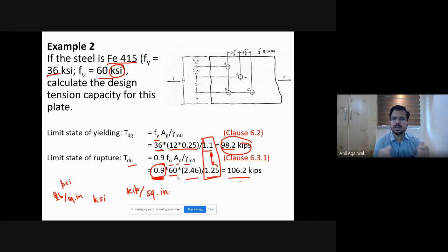What happens is that when you have a plate like this, and let's say you have some imperfections for whatever reasons, like the holes are not perfectly drilled, then the actual rupture strength of the plate has much more scatter, or predicting the rupture strength of the plate is much harder. You understand? So geometry also plays a role. It is not only the yielding of the coupon, because a coupon is cut very nicely with smooth edges and everything.